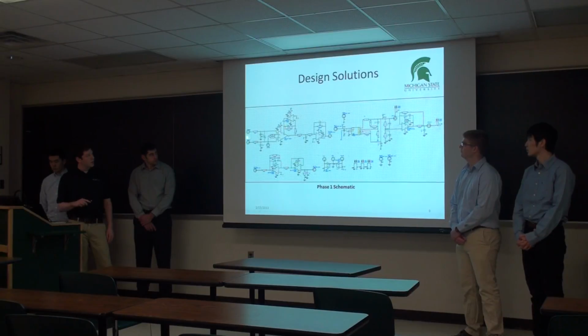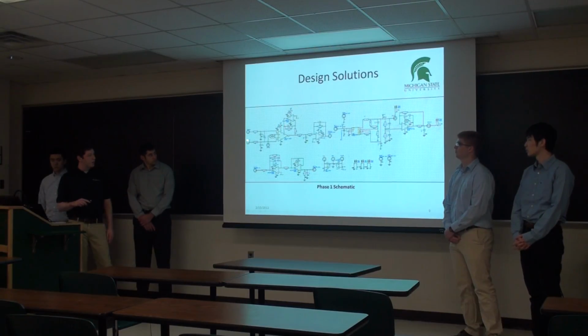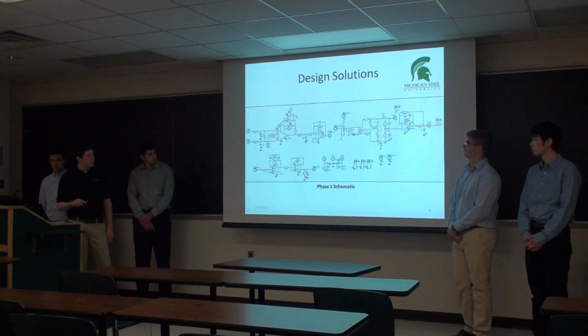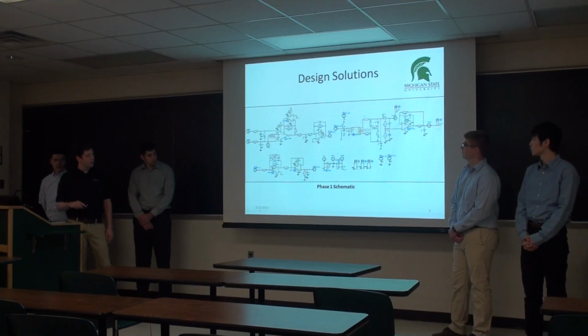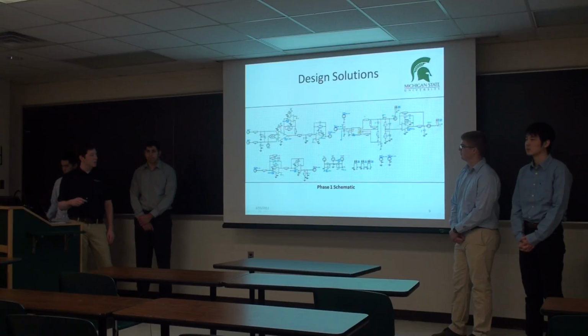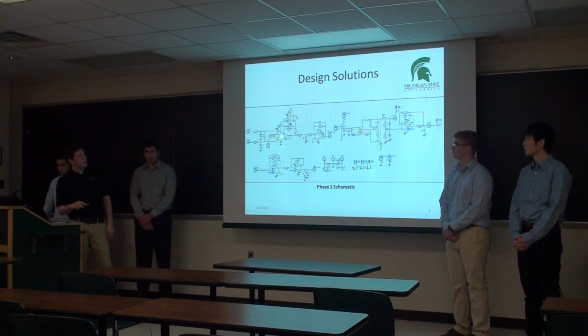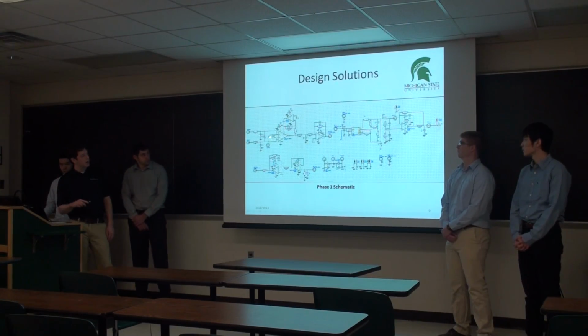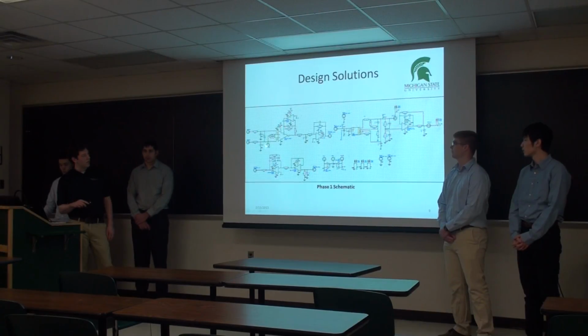For this stage, phase 1, we separated these things with test points so that we could test each individual circuit to make sure everything was working. Later designs will connect it all together to be one full circuit. Right here we have the INA with the gain setting, the splitting of the common mode voltage that will then go to the right leg drive, be inverted and gained up a little bit, and then sent back to the body.